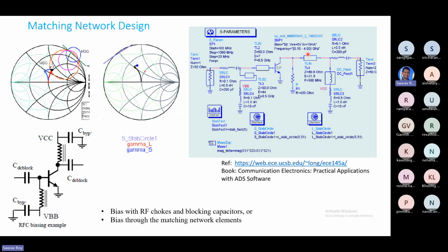In the low pass filter, a low impedance line, microstrip line, can represent a capacitor. So now here we are interested in adding an inductor that can be done through a particular length of high impedance line. That is what we are adding here.